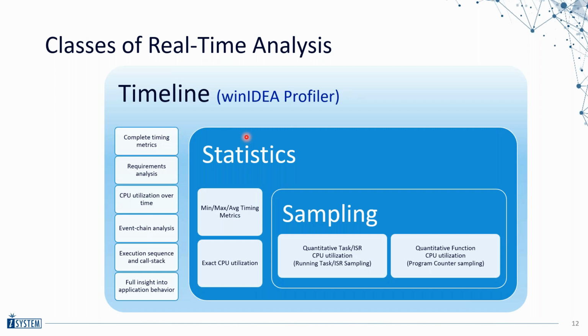And then you would get certain metrics like the gross and the net execution times of your tasks, ISRs, runnables. And the cool thing about that approach would be, firstly, it's probably more precise than sampling, depending on how you implement it. And secondly, you could also remember the min, max, and calculate the average metrics. So you would get a more detailed picture of the timing behavior.